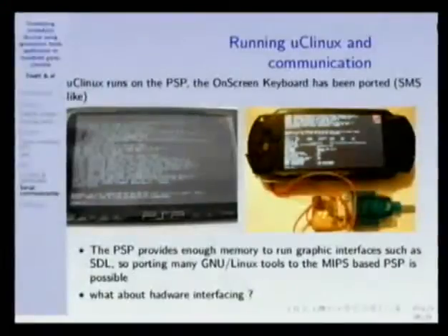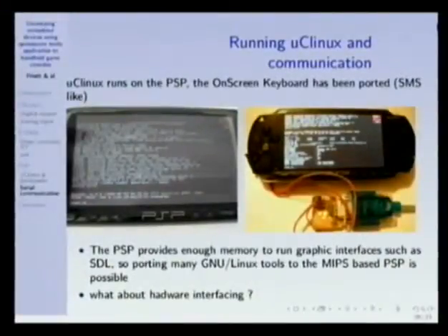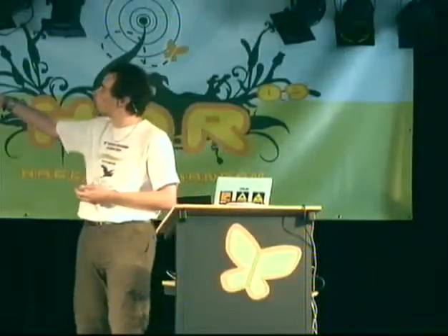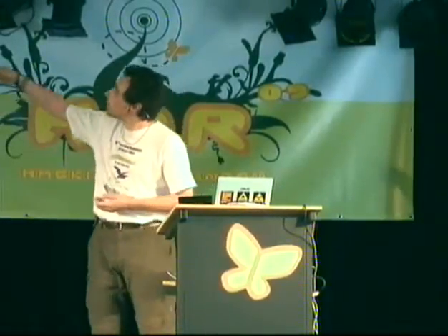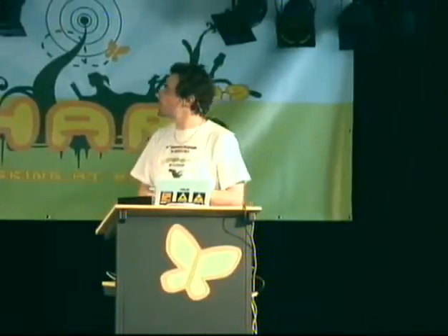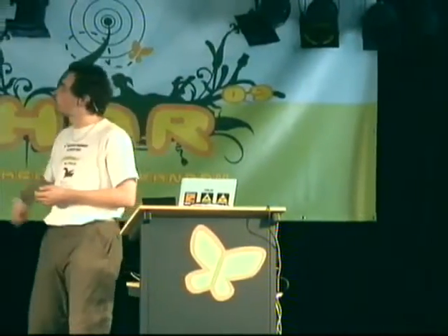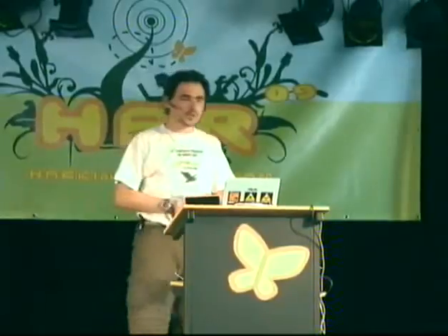with your shell here. And unfortunately, I will no longer be able to discuss hardware because there is simply no hardware port available on the PSP. The only piece of hardware that you have available is the serial connector next to the headphone jack. And what you can do is connect an RS-232 level converter so that instead of typing using the on-screen keyboard tool that is provided on the web for PSP, you can type your commands from your PC and the PSP appears as a terminal.